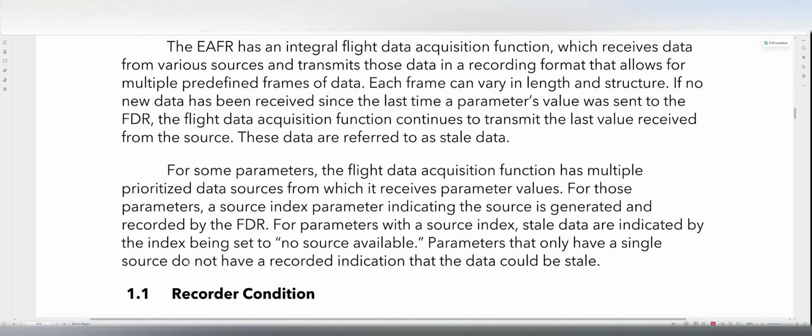Now that's interesting. The switches do have two sources, the switches themselves. They've got left remote data concentrator and right remote data concentrator. And if they had switched to off, both of those data concentrators would have seen the off signal.